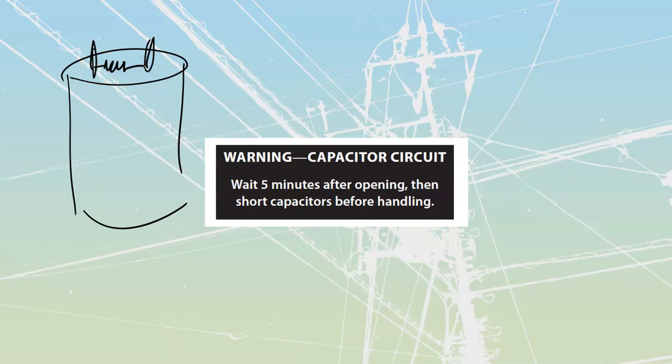It's high enough, in the 50 k ohm, 100 k ohm range or something like that, that it's not always draining current from your load. You don't want to be running a lot of current if you don't have to. But whenever the power gets shut off, it is going to allow that current to drain from one side of the cap over to the other. Usually they're going to require at least 1 minute for low voltage power factor correction capacitors, but anything that is high voltage is going to be up to 5 minutes.